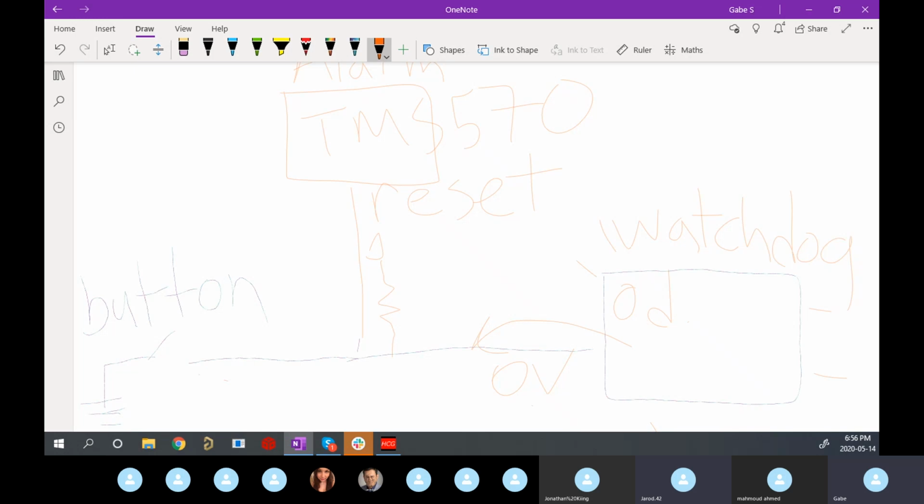Questions? So when you're doing this redundant shared line alarm, all systems on that line have to be open drain? That's right. If you have one that's push-pull, and it thinks it should be 3.3 volts and sends 3.3 volts, but everyone else disagrees and says it should be 0, you're going to have a short problem. That same line is going to be forced to 3.3 and 0 volts at once, and something's going to get damaged in there.